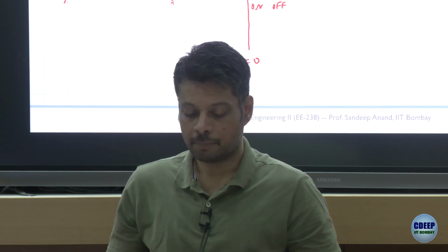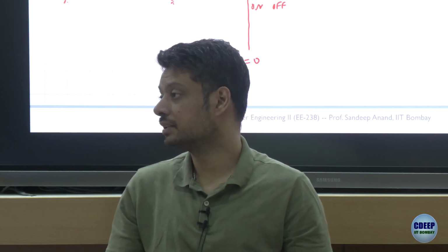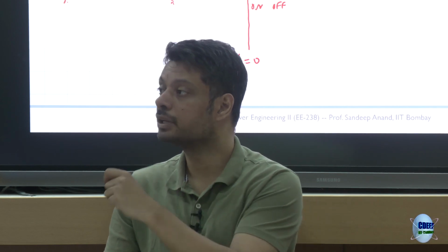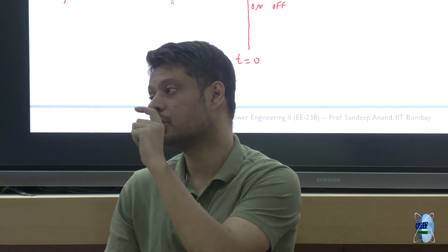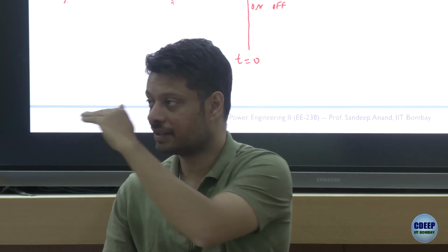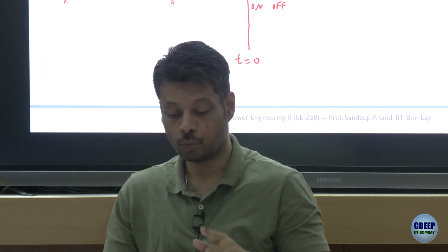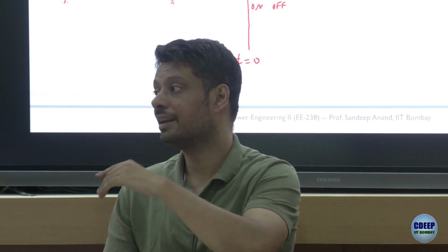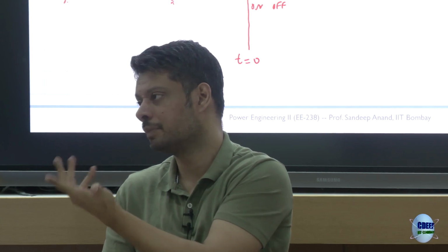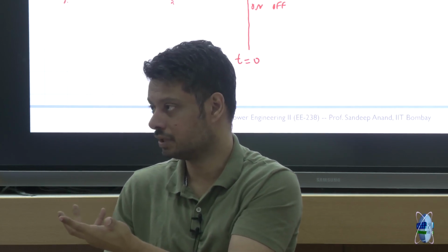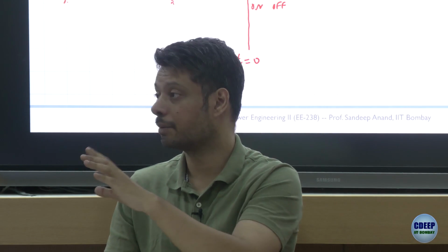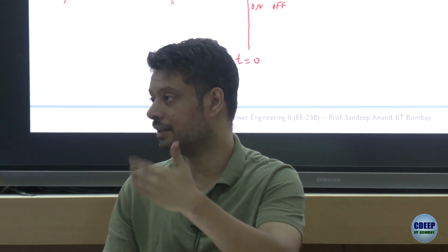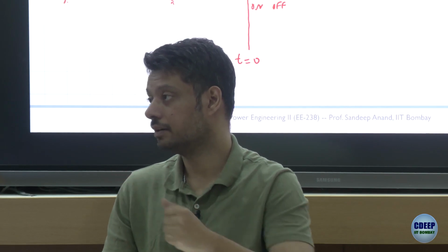Practically, let's say you are using this rectifier circuit to charge your mobile phone. Now, what do you want? The 5 volts coming to your phone should have a very small amount of ripple. It should be more or less a constant 5 volts. So ideally, you want the capacitance to be infinitely large. And the resistance is the load, which is determined by the phone itself, so you don't have much say in that. As a power supply designer, you want the capacitor to be really, really large. Therefore, it will not even be B, it will be something above B in a way.